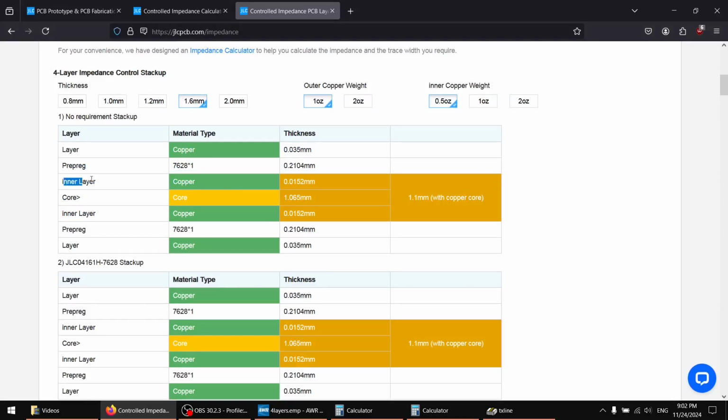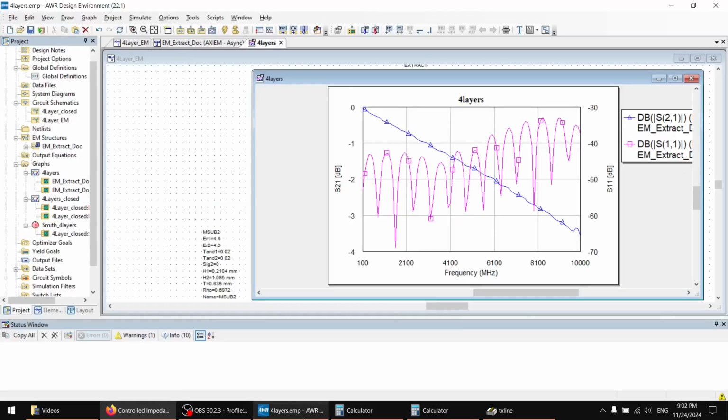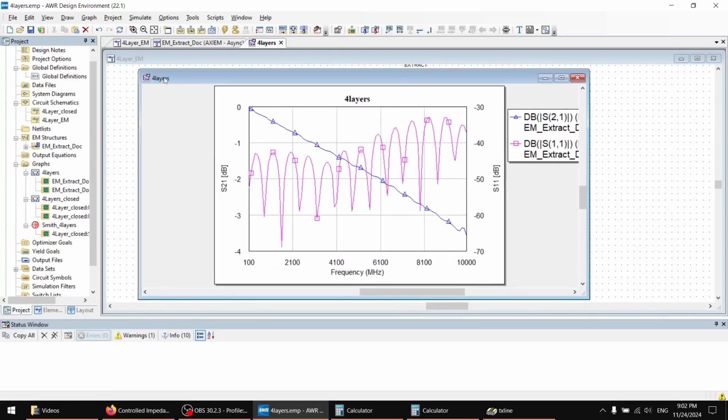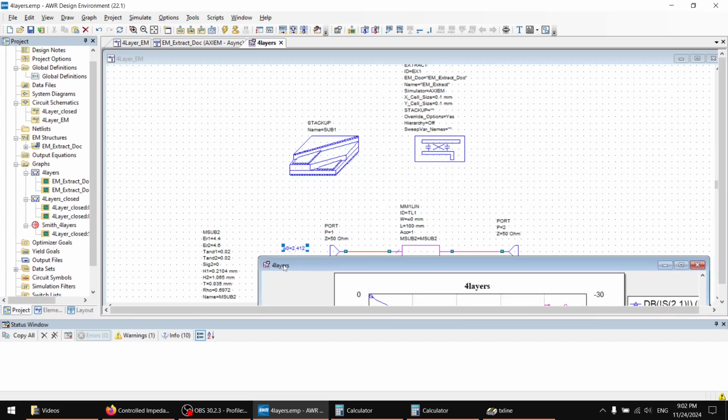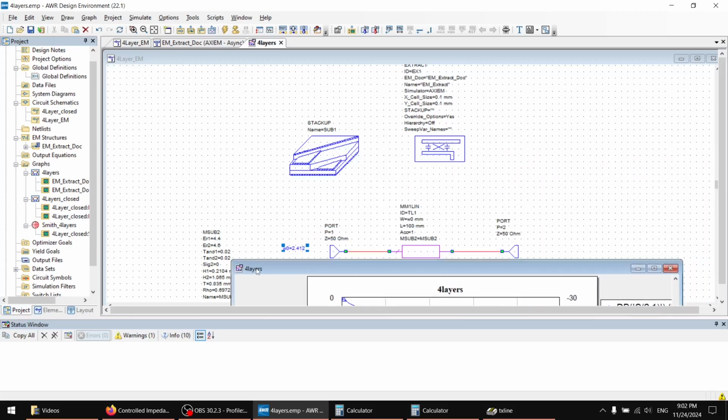You can omit the pour on the first inner layer, and use the second inner layer as a ground plane. So concluding, the combination of these layers gave us a stack-up that is quite useful for microstrip structures, because the width of a 50 ohm trace is quite reasonable, and the width of high impedance traces will probably be possible to manufacture.